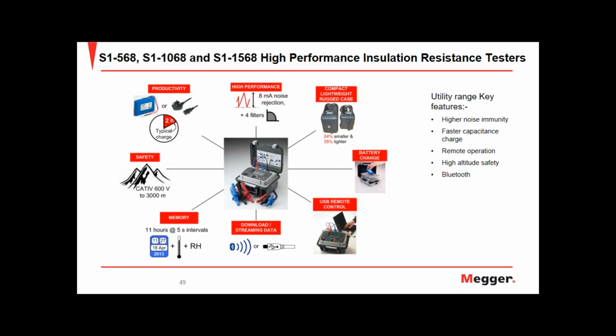But if it is too long, then it's still going to take some time. So the key here is that you are charging the insulation. So instead of doing a 1-minute test or a 10-minute PI test, as Nick was explaining, you can hold the test there for a longer time so you can charge that capacitance and get an accurate result.